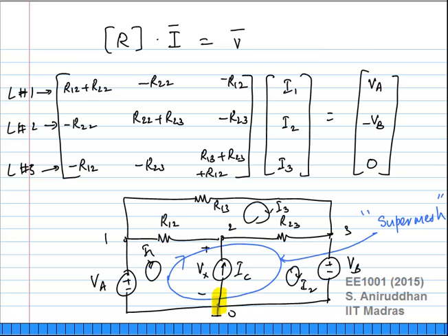So the additional equation is I2 minus I1 equal to IC. In other words, the additional equation I am actually writing is KCL at this node. Just note that. In fact, in the original case of the super node for nodal analysis, we actually applied KVL there. Even though we were writing KCL for everything else, the extra equation we got from writing KVL. Any questions?